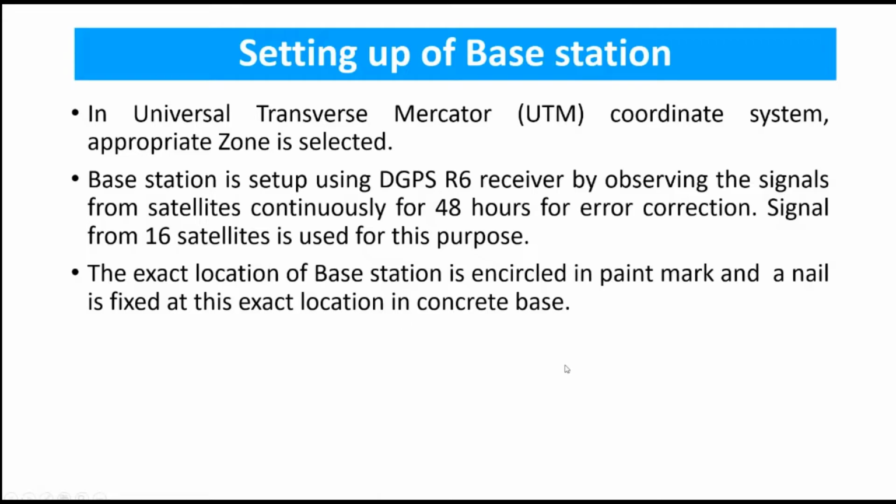The exact location of the base station is marked with paint and nail. So whenever we have to mark, we insert the nail and mark the exact location with paint, on the concrete base, so it is a permanent type of thing.